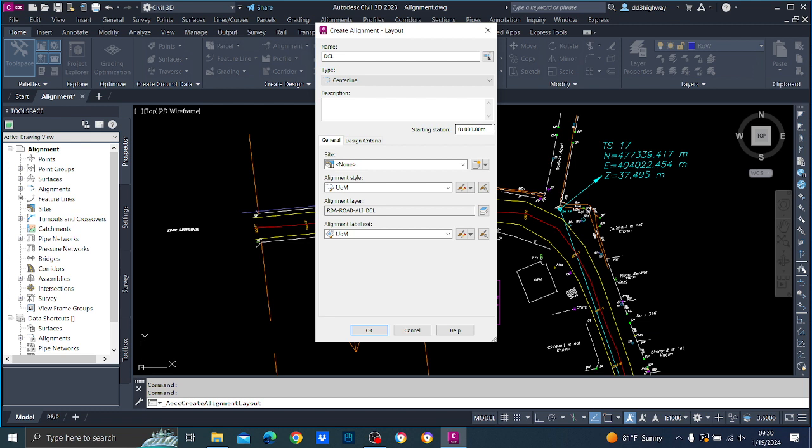So you may be wondering why we have to change it, because just think that you are going to go and start somewhere in Anuradhapura. So in Anuradhapura, maybe the existing chainage may not be 0. Maybe it is some 200 something. In that case, you can of course have your correct starting station. And then site. There are no sites available. You can create a site.